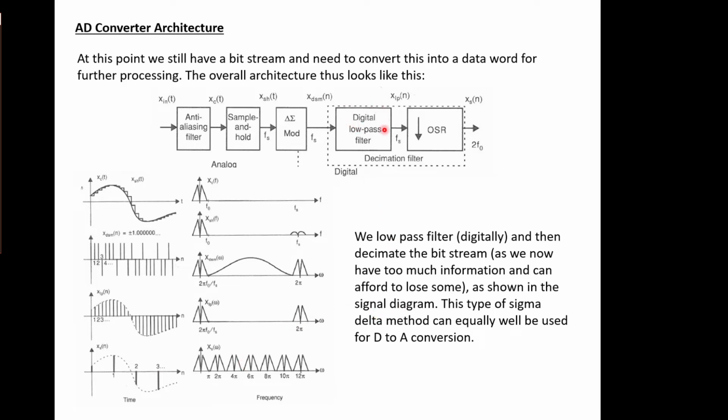Actually building this digital low pass filter is quite a hard job to do because it needs to have a very good response, but decimating it's quite easy. So we move the complexity into this part here, and that's not part of our course, you'll be pleased to know, so we don't worry too much about that. That's where you really need to understand Z transforms. And I'm sure some of you have done digital filtering courses, so you'll be familiar with what could go on in here.